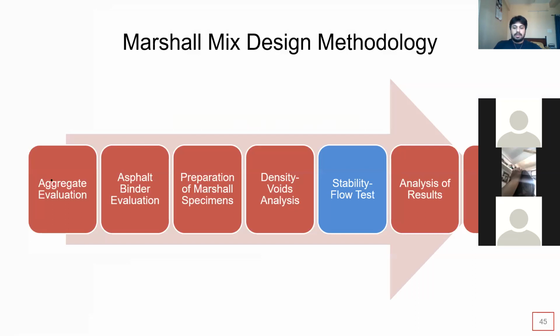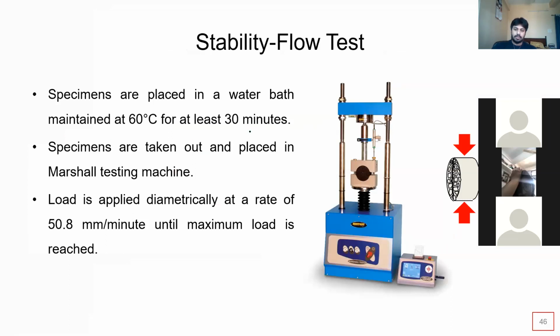Now you have to test the sample. Test the sample means the Marshall cylindrical sample. That sample should be tested using Marshall apparatus. That is Marshall apparatus. That's why it's called Marshall mix design. Okay. So this is stability flow test. Stability flow test.